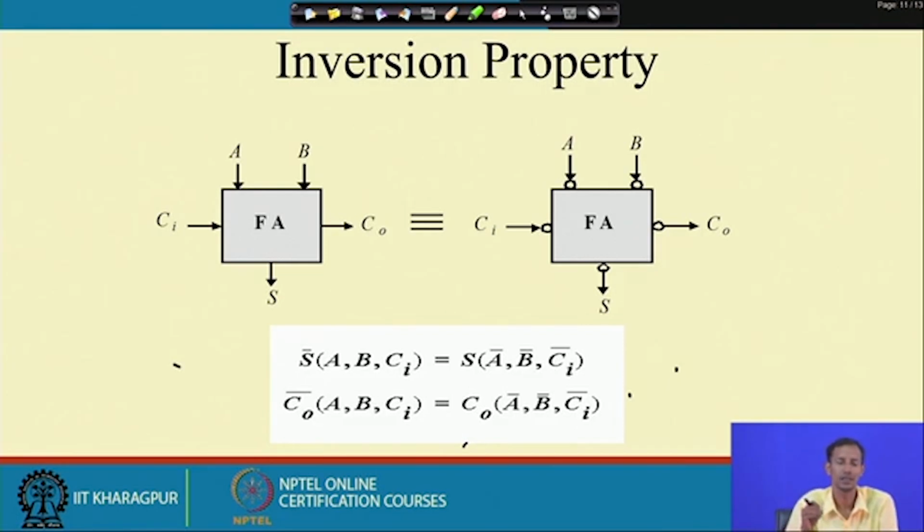If you see the transistor, that means NAND gate level implementation, at that time you have to put one inverter at the output, as the operation is coming as NAND operation, but I need AND operation. So, I need one inverter at the final output for making the NAND to the AND.